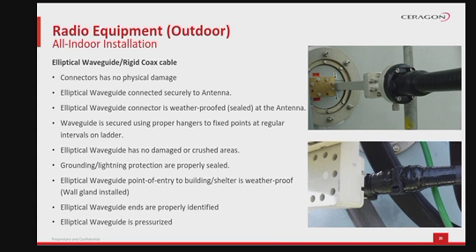The activities also include verification that the waveguide has no damaged or crushed areas, and the grounding or lightning protection are properly sealed and labeled as per customer requirements. Verify that the waveguide is correctly pressurized following the test procedure for the waveguide dehydrator.